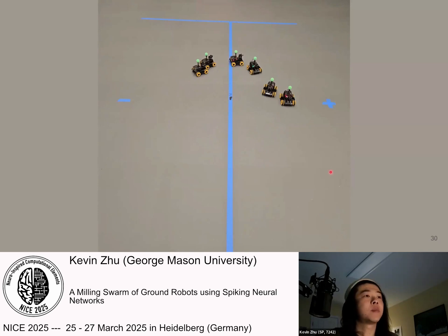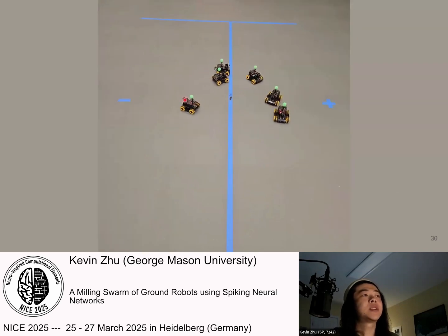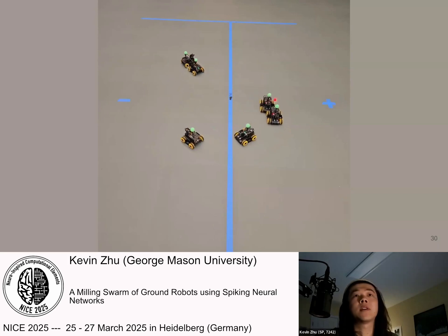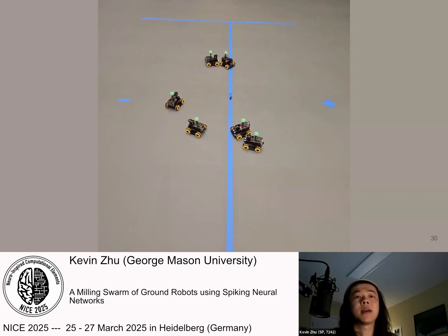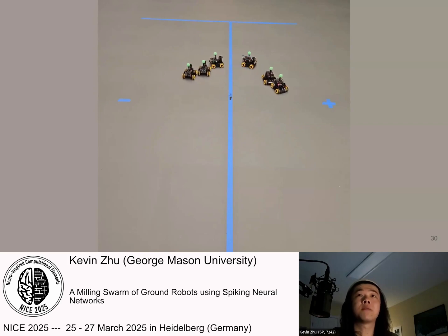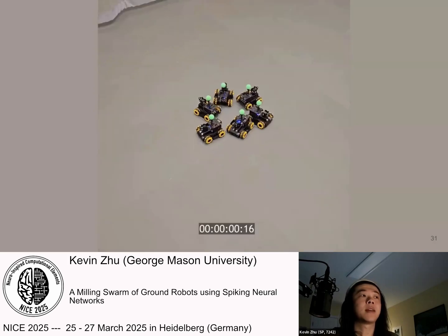Here we saw that the robots seem to turn actually faster when they're not going forwards, when they're turning on a dime. And this was somewhat unexpected. Our linear mapping did not account for this. So a simple trick was simply to prevent them from moving with zero on either forward speed or turning rate. So they're always moving either forwards or backwards and always turning.